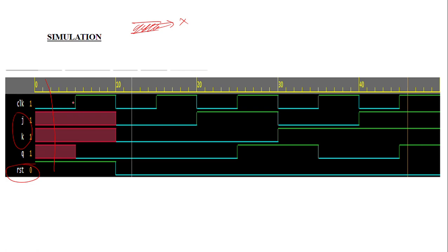So there is another reason. When is your always block going to be executed? Whenever there is a passage of clock, only then your always block is executed. Before that there is no passage of clock, so it takes default values, meaning unknown values. After the passage of clock only, our flip-flop, or our design code, recognizes that the reset value is 0. So after this passage of clock, your output is going to be 0. Reset is active, which means your output is automatically 0.